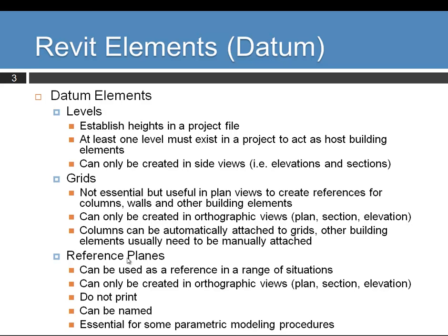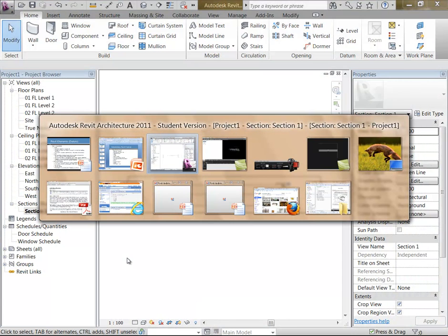You can use them in either side views or plan views. And they are really, really useful. That's why we always start with those. A lot of people don't. A lot of people just get in and start drawing walls and things, and that's fine. But you'll find once you're doing anything that's a little bit complicated, if you don't know how to use reference planes, it can be difficult, or in fact, for a lot of things, it's impossible to do some operations without reference planes.